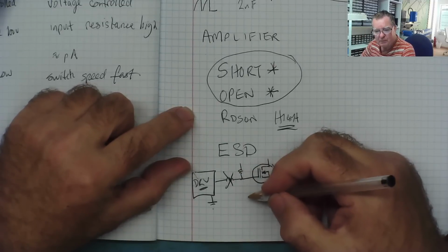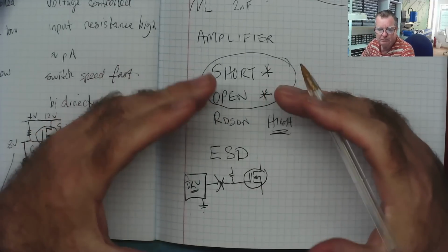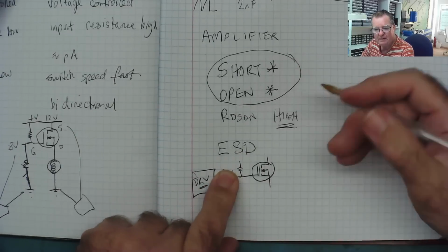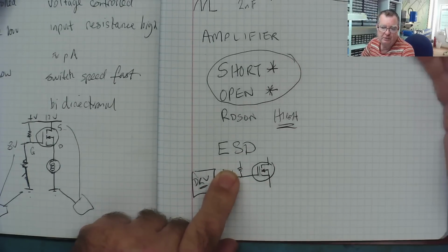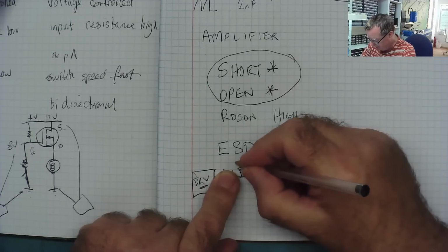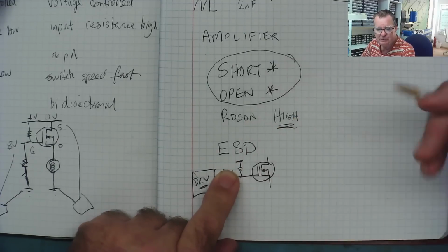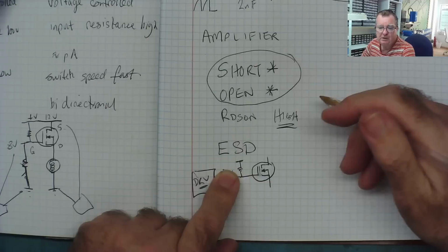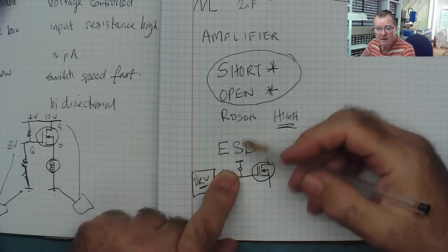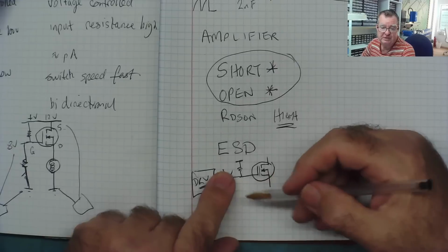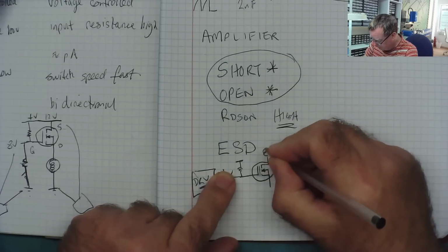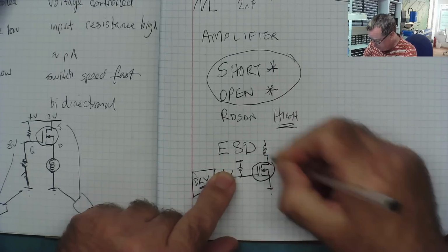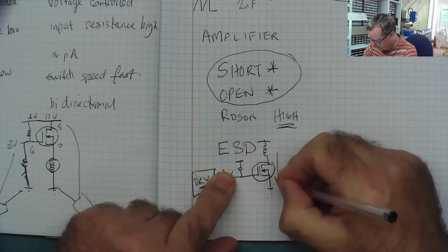What happens now? You might think, well, the MOSFET's got no drive, the resistor isn't there. So when I power up, it's got no drive. Well, it might have a pull-up resistor, and that will instantly cause the MOSFET to turn on. In which case, because this circuit isn't there, that MOSFET comes on and stays on, and whatever circuit it's supplying, power runs down through here and the whole thing goes short again.